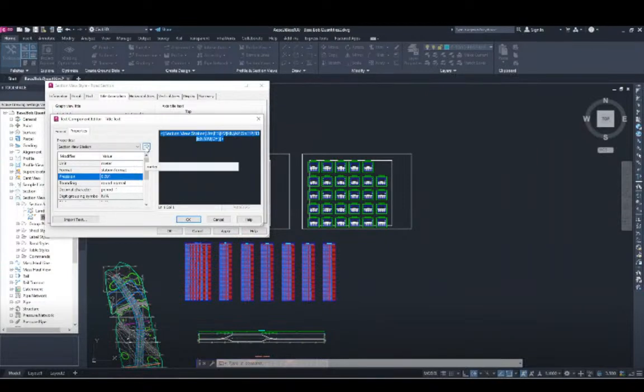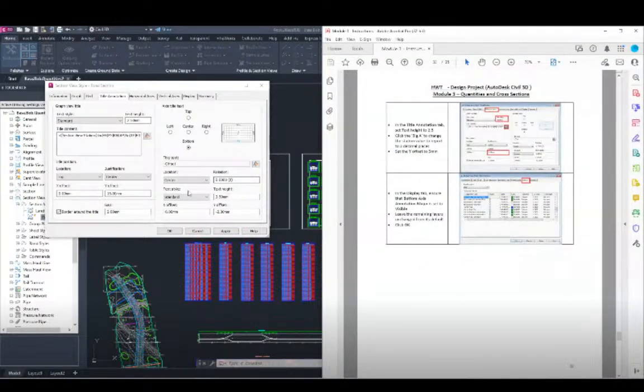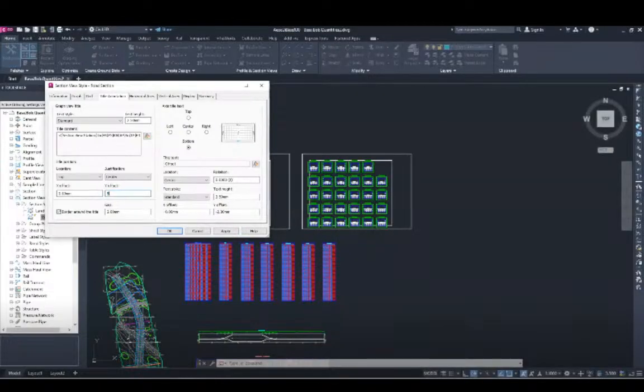We're going to click the arrow. When you do that, you see it change. It should change this to say P3. That means it'll be 3 decimal places of precision. I'm going to hit OK there. It says P3 there, so we know we did an OK job. Set the Y offset to 5 millimeters. So that's another thing we have to change here.